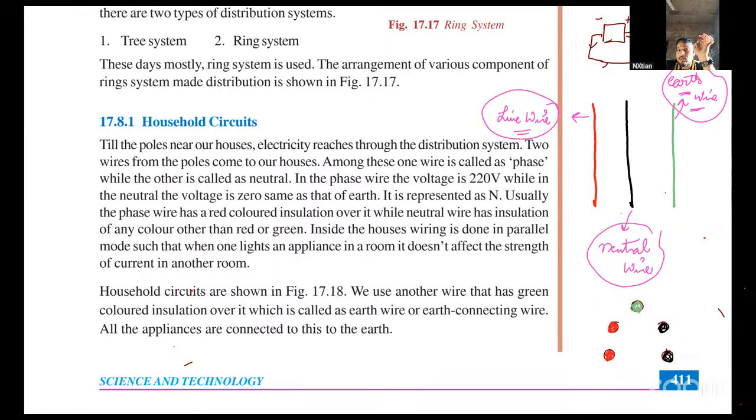So basically, the electricity is coming from the red wire, and we are working as a negative terminal going towards the earth, so the circuit will flow. The red wire is positive, and electricity is flowing. When we touch the tip of the tester, we are making an electric circuit from the positive terminal through my hand to the earth, the circuit is formed, and the bulb will glow. But if you do not touch the tip of the tester, the bulb will not glow at all, because the circuit is not formed.